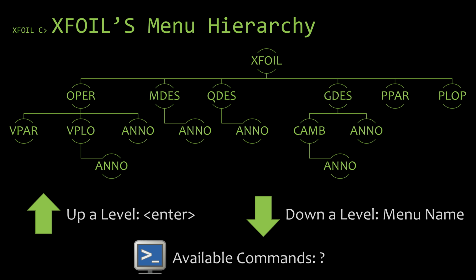So what you see here on the screen is a tree of the different menus. These aren't the commands. Each of these circles, each of these menus that you see here on the tree, would actually contain its own list of commands or scripts. So since Xfoil is arranged into this hierarchy of menus with the different commands on different menus depending on where you're at, it becomes important to know how to navigate this tree.